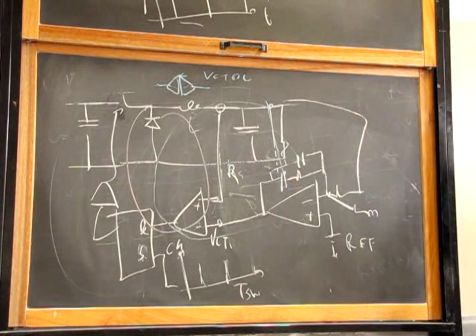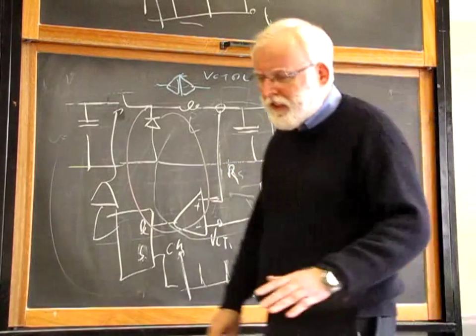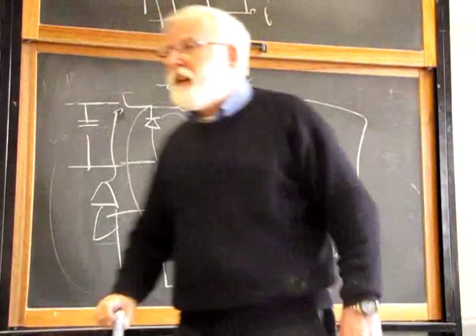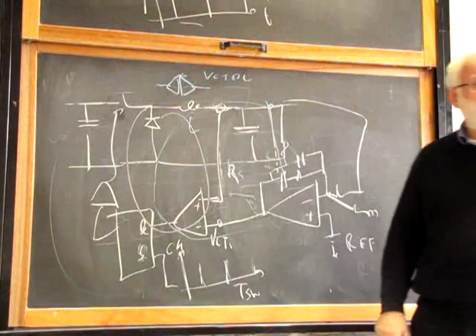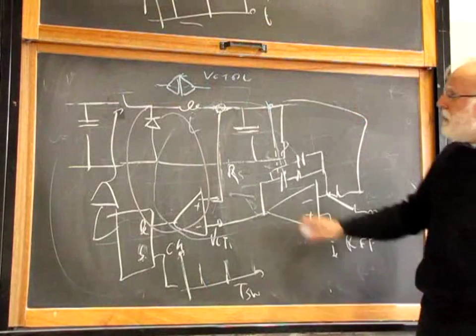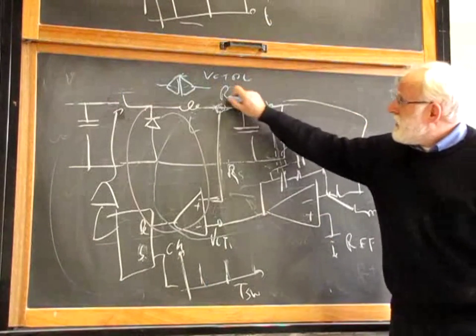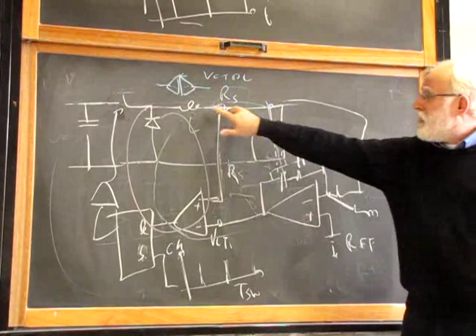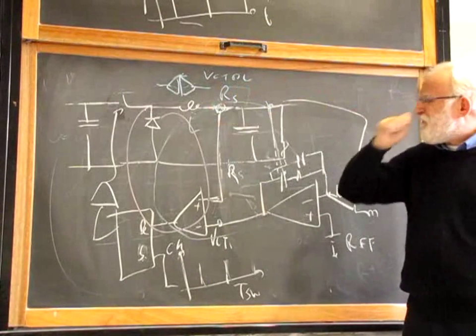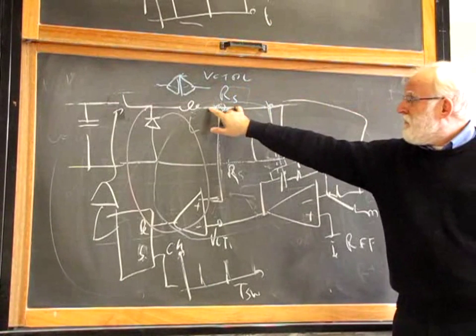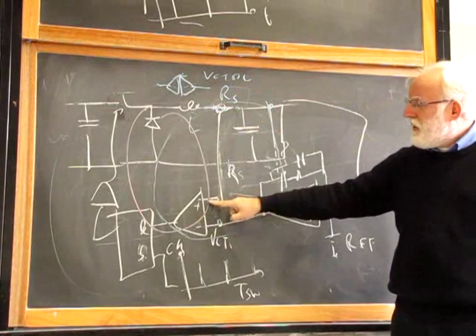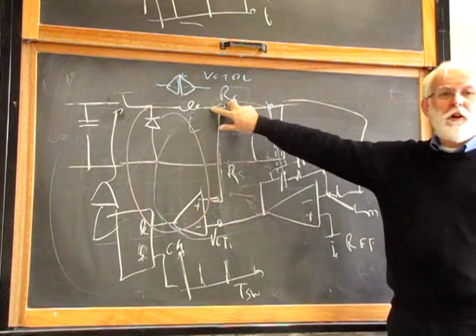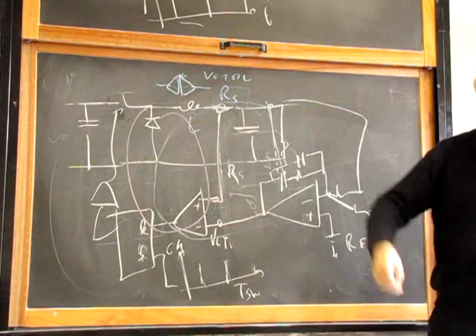Well, there is just a detail, and the detail is, let's suppose, it's not the only way, but it's a common way to measure this current with a resistor. So, the voltage across this resistor has a value IL times RS. The voltage across this resistor is what is compared over here. Here it's a single-ended input, here a differential input. It's not a big deal.